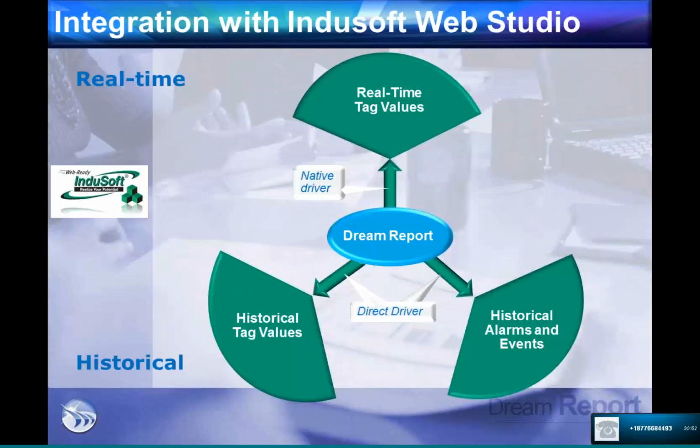Integration with InduSoft Web Studio. So here we are talking about three main parts, native parts, how we communicate with InduSoft Web Studio. So first of all, we can create direct link to real-time tag values and store those values inside the Dream Report database if required. We can also create reports on top of existing historical tag values, which are stored inside